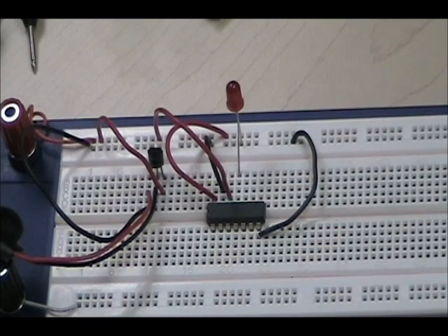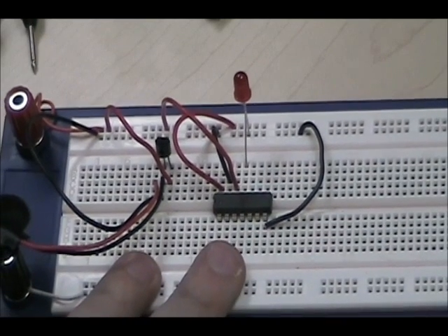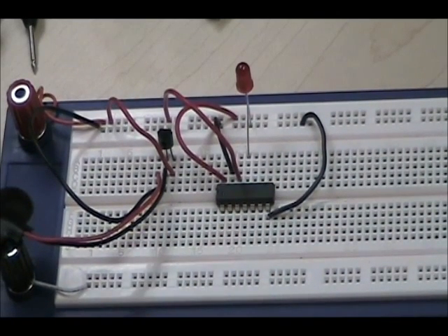Okay guys, this is a NAND gate. So remember, the output of an AND gate will only go high when both of its inputs are held high. So oppositely, if we turn on the power and put both of the inputs high, then the output will go low. Otherwise, no matter what, the output will stay high. Now remember, if you need to go back, simply Google NAND gate or AND gate, and you'll get a truth table of it. But try to remember it, because it's not hard to memorize.